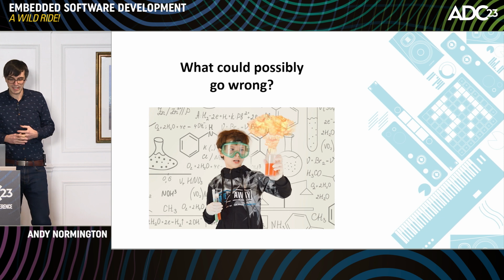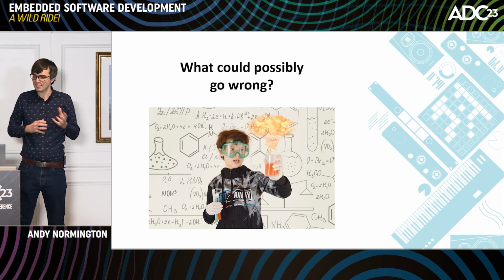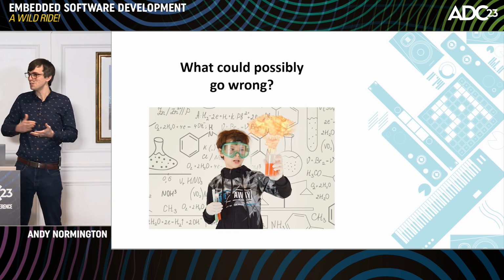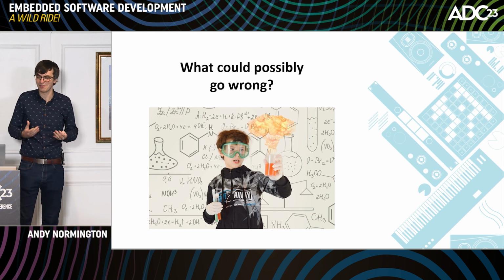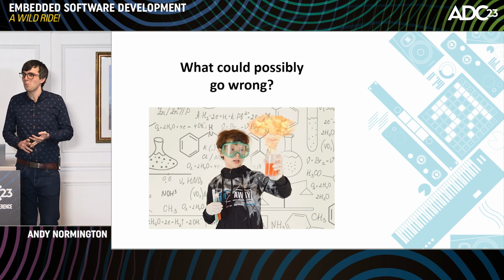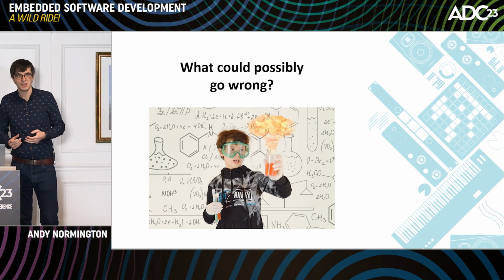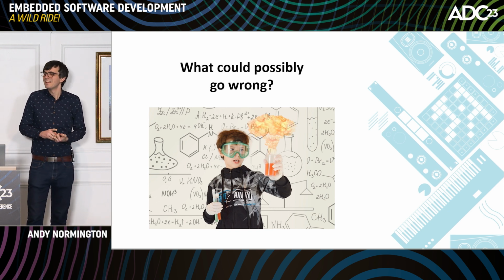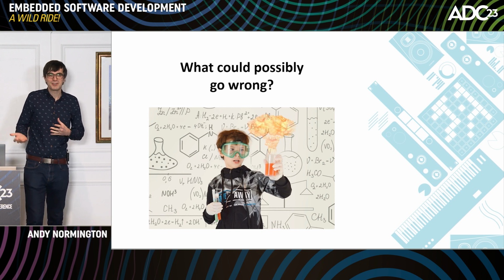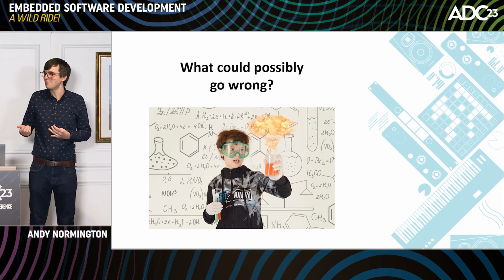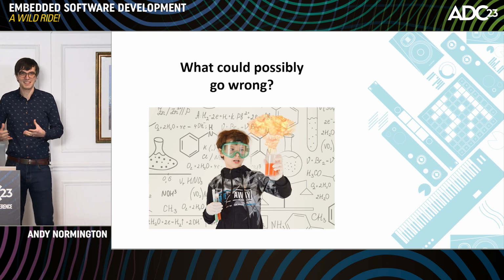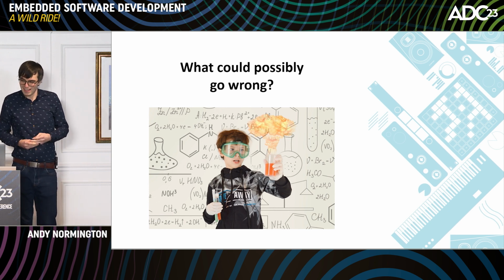So we want to do some work now to do some sense checking of those things, to validate those assumptions before we get too deep into this choice of microcontroller and the configuration. We're going to think about where are we pushing the limits of the microcontroller? Where are we going to burn all our CPU cycles? What about those RAM estimates that we made? Could we be a couple of 100 bytes out, or is it possible that we might find a few 50 kilobyte buffers that we just can't even fit in the RAM?